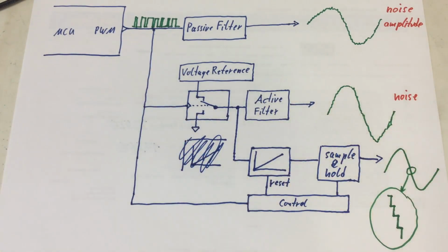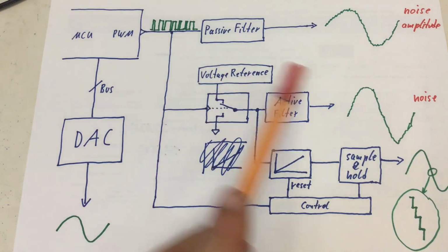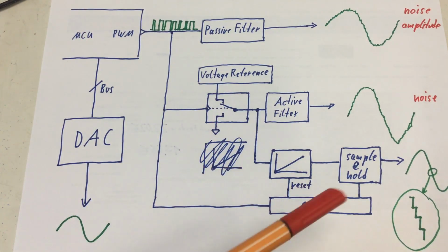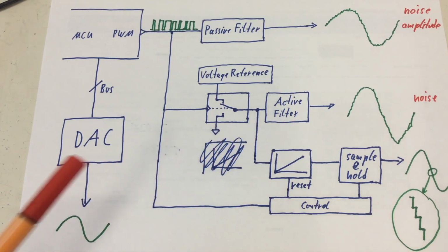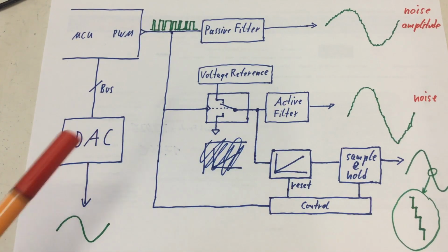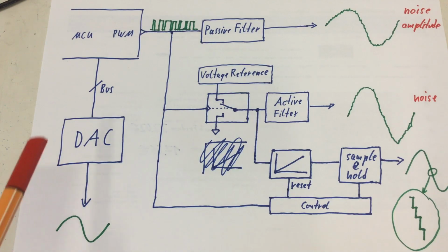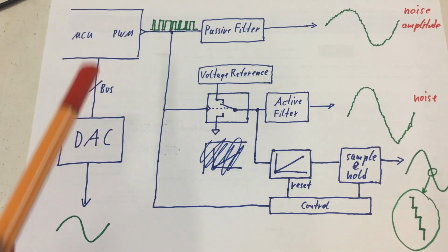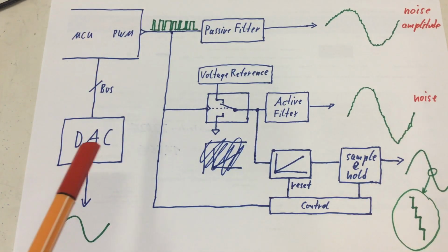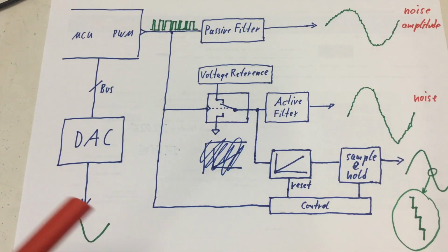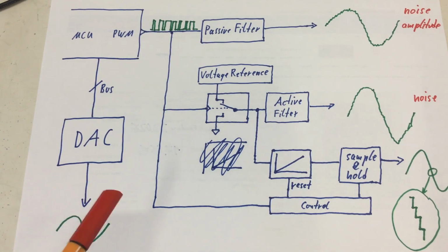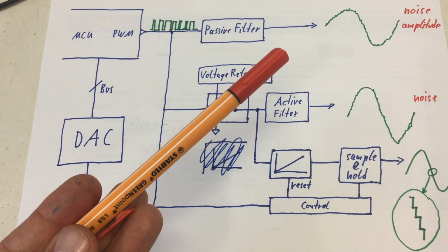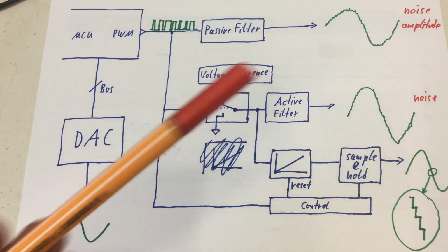Very nice. By the way, the whole shebang, if you include the PWM generation itself, is one possible architecture for a digital analog converter. And you can buy those. And they talk directly, digitally with your MCU and output a very nice, very precise, very low noise analog signal. But that's something for an upcoming video or two.